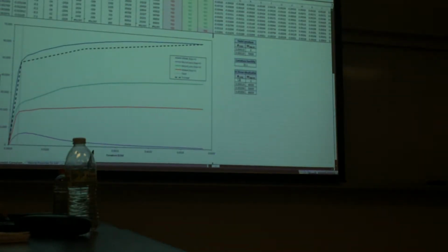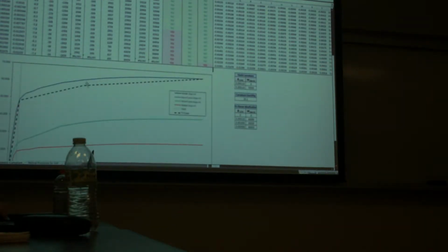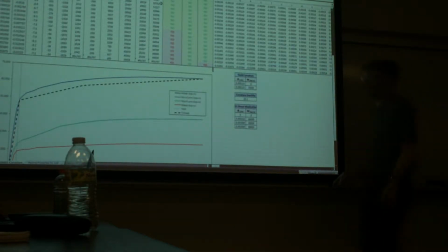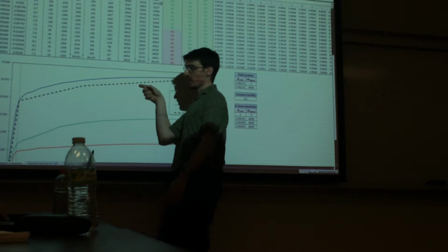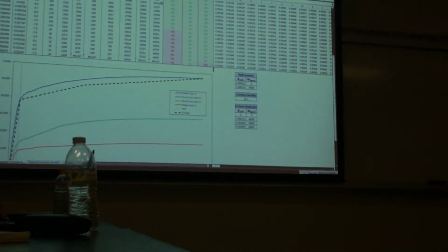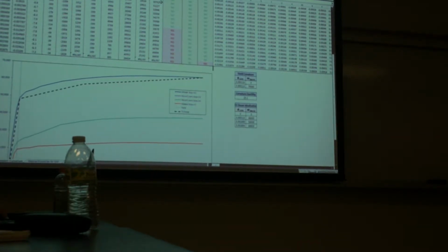In this case, I had a trilinear idealization here. But that changed for some reason. Oh, and I had the fifth fiber in, I forgot to change that back, but that's fine. You could come up with different idealization models for this, and there doesn't always have to be an empirical equation for that idealization. Caltrans generally says to do an elastoplastic moment curvature analysis, where you come up and then just go straight over. So there are different ways of doing it, depending on what field you're working in.